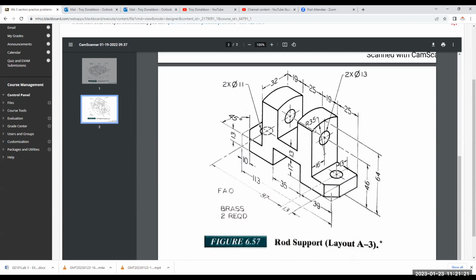Notice this R35 comes from the top, this 64 number comes down, and then that's where the radius is swung. So just look at it carefully when you go to draw it. Try and pick out those dimensions. I hope they all add up. There's a few of these drawings where the dimensions literally do not add up, which is not good. So if you come across one, just make an assumption and go for it and put a note on the drawing.